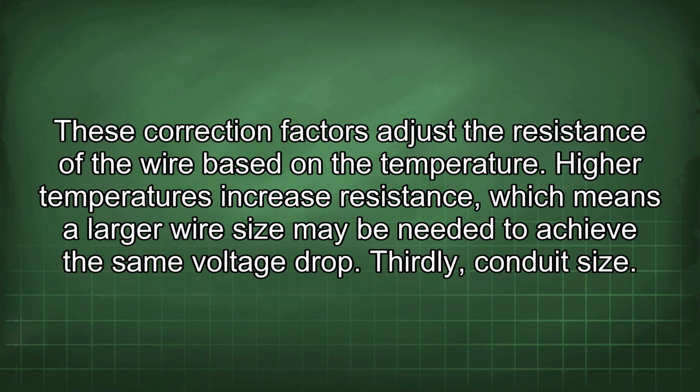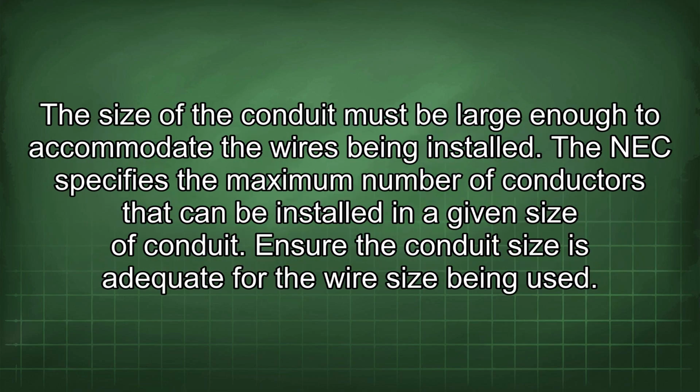Thirdly, conduit size. The size of the conduit must be large enough to accommodate the wires being installed. The NEC specifies the maximum number of conductors that can be installed in a given size of conduit. Ensure the conduit size is adequate for the wire size being used.